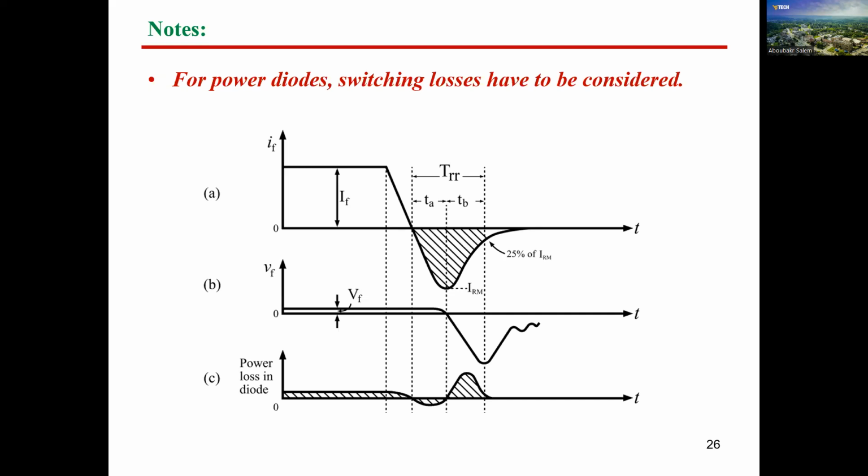For a power diode, current is high and voltage is high. Can you see, guys? This is the turn off characteristic here. The first curve represents the turn off characteristic. This is IF, which is the current during forward biasing. When the diode is turned off, as you can see, it's not going to be zero and stop instantaneously. No, it will decrease, and then due to the reverse recovery, it will move like that and return back again.